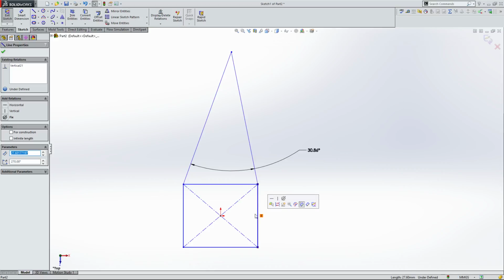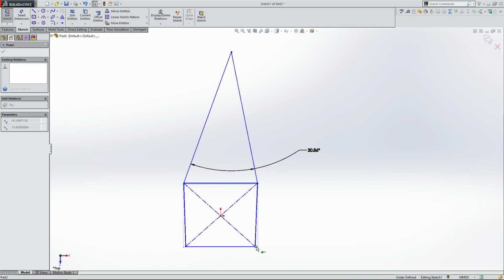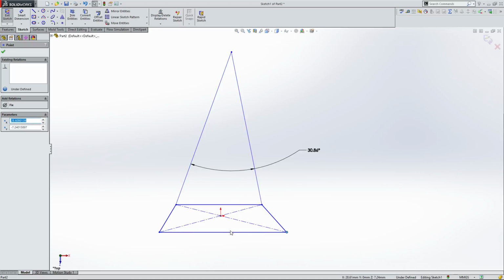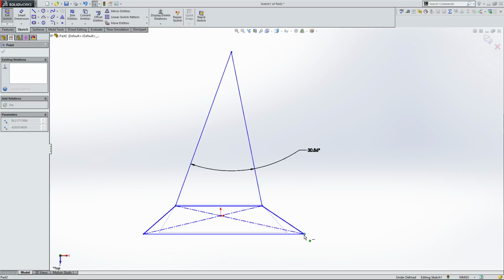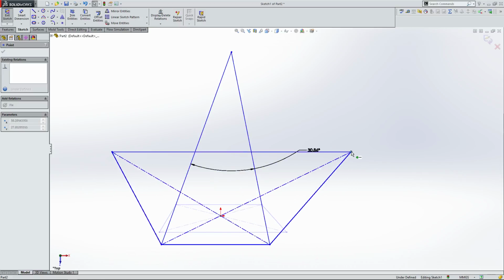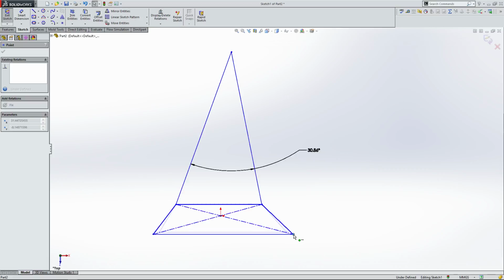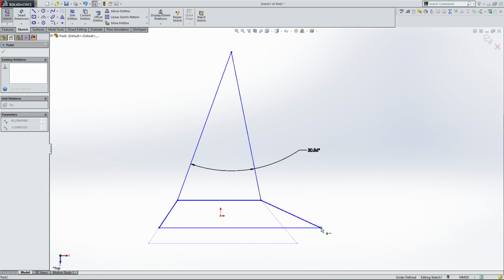Another thing is, these lines are vertical, but if you want to, you can delete these two vertical constraints, which is going to allow you to move your two lines any way you want. Now, of course, these two are still constrained, so they're both going to be parallel. The top and bottom lines are parallel, but the ones on the left and right, they can move at whatever angle. So as you can see, you get a really interesting control over your shape. And of course, this has these extra lines, which changes things.